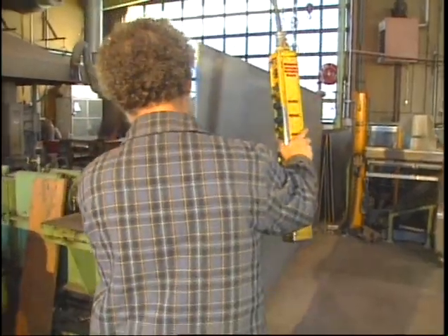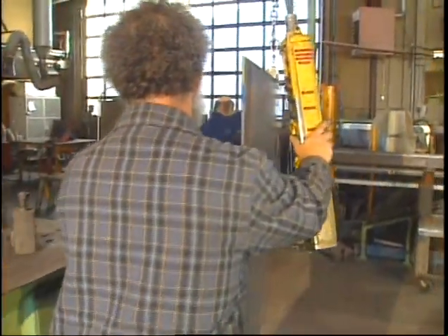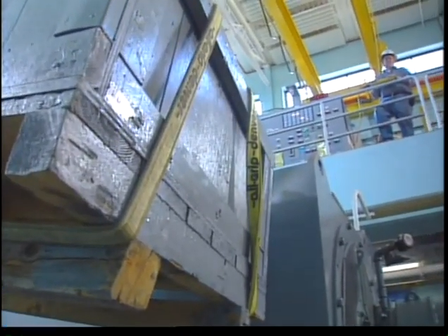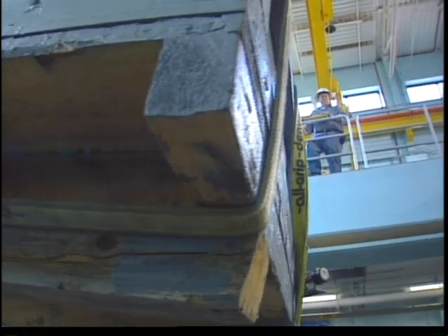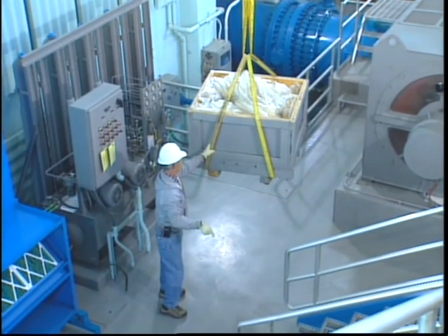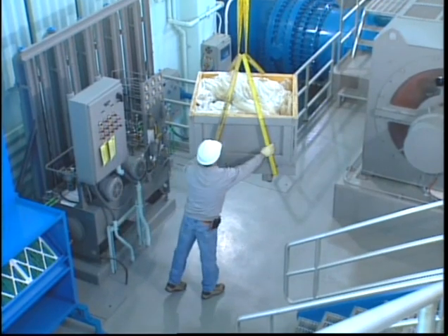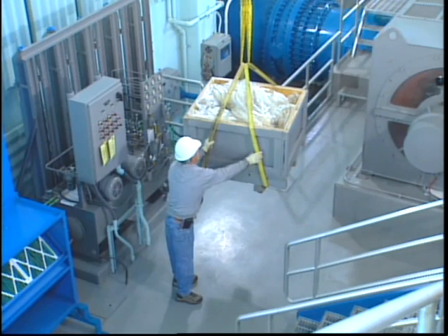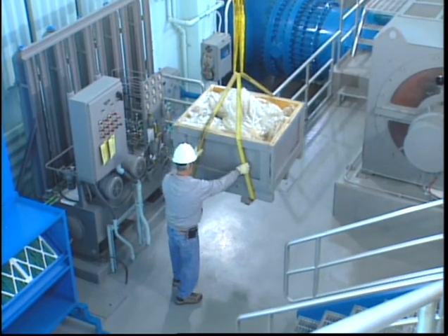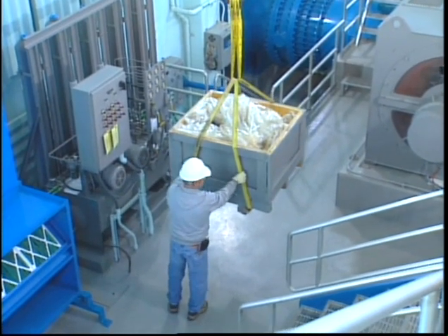Never lift a load over the head of workers and never leave a load suspended. Don't allow rigging crew members to stand next to or stand on the load while moving, as they could be trapped or hurt if it swings. When it's necessary to help balance and control the load, do so carefully by positioning your body in a spot where it can't be trapped, or use guide ropes that can be controlled from a distance.